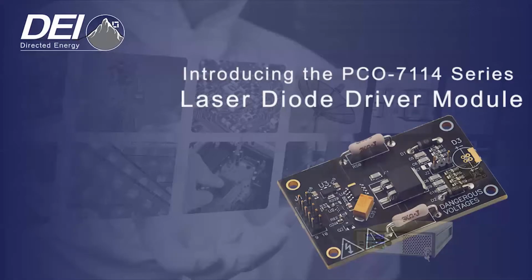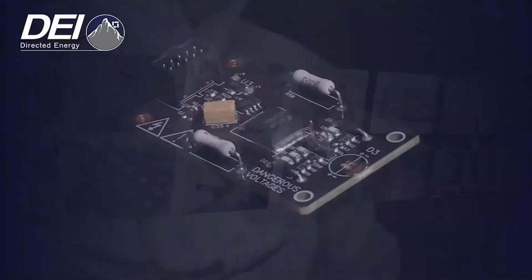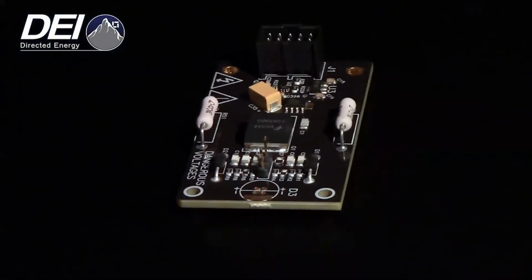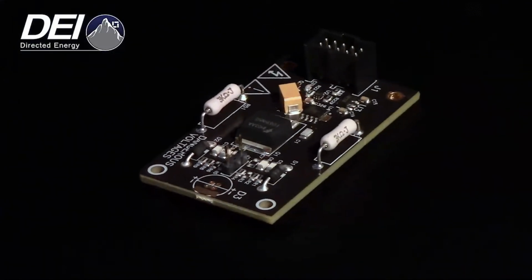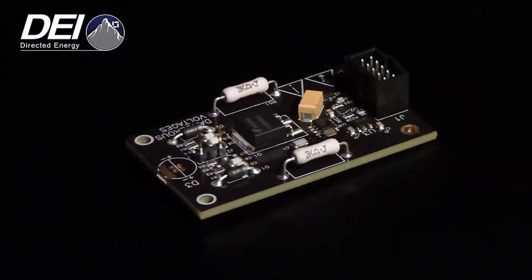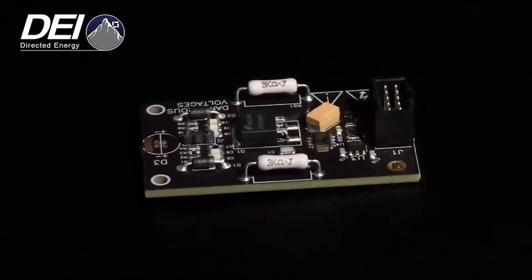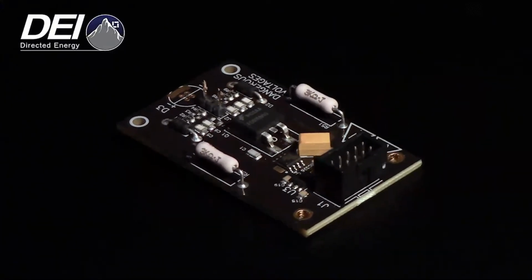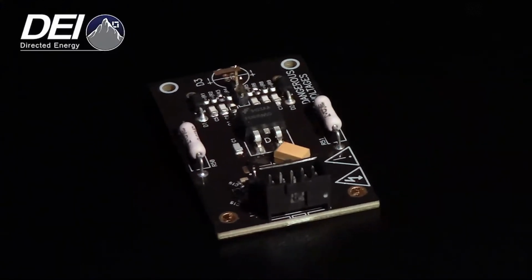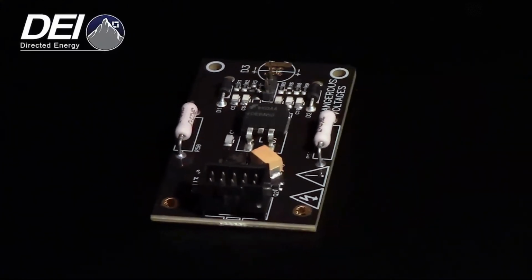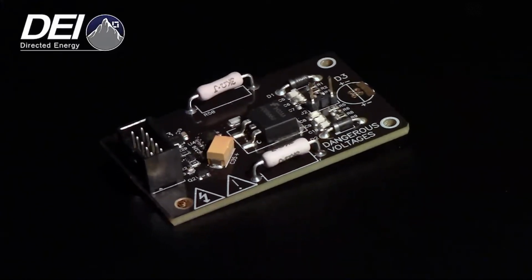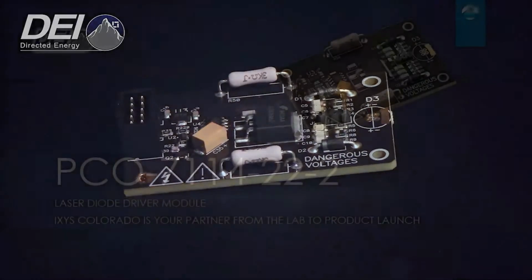The PCO-7114 is a series of laser diode driver modules that provides from 6 amps to 50 amps of pulsed current at frequencies over 1 megahertz. With configurations covering a wide range of operating conditions, this versatile module is ideal for extremely fast, high-current, pulsed laser applications, including ADAS, LiDAR, range finding, and research for both OEM designs and single-end use.